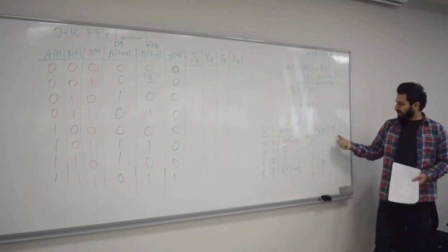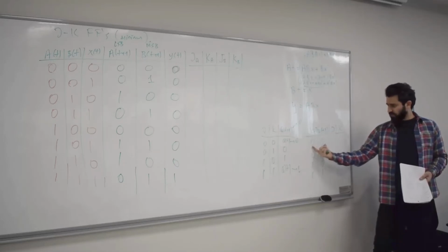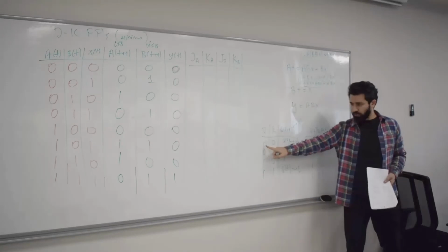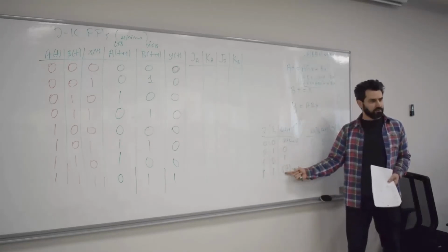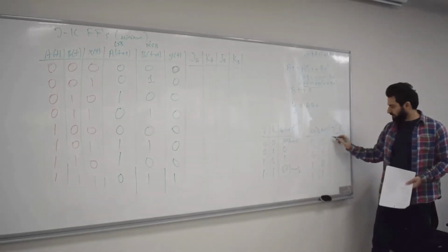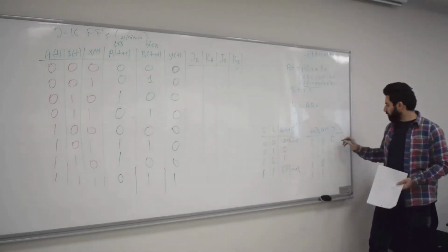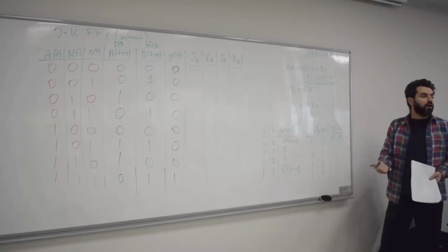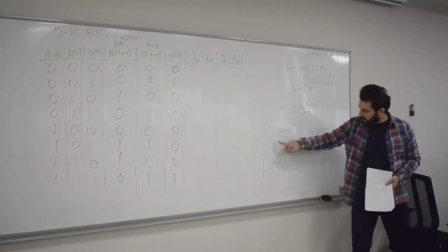So, you can see that in this particular case, if I see 0, 0, the inputs J and K could be 0, 0 or 0, 1. These two cannot be, okay? So therefore, I put J to 0 because it's guaranteed to be 0. But K could be 0 or 1. That's why I'm going to say, don't care, because it could be 0 or it could be 1. Both are possible. Okay? How did you decide that? Because K could be 0 or 1.